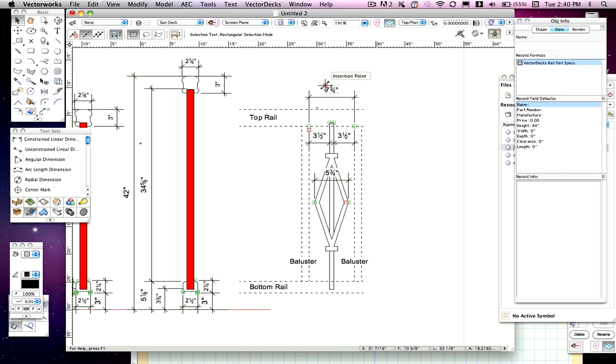And that tells VectorWorks, when you have a rail system and you have all the rail balusters all the way through, that when we insert this, it needs to go in the center and make an opening 7 3/4 to allow this to fit and still conform to all our code requirements. And then from these 2 points on, your rail-on centers will be placed. So we know we need 7 3/4 inches clearance.